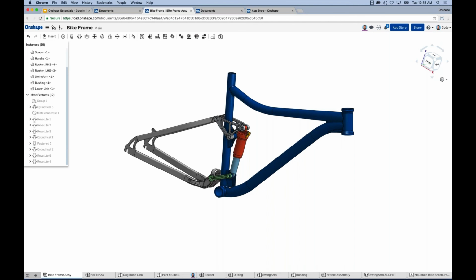Next question, is it possible to restrict the motion? Yes, in all the scenarios, whether it's angle of rotation or linear travel, all of the mates with movement have an option for limits, and you can punch in how far you want to allow it to move. So definitely do a search for that if you're interested.